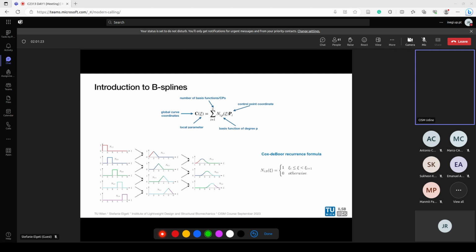Well, here we always have an overlap. So for linear, we have two basis functions that overlap in each knot span. For degree 0, we don't have any overlap at all. And I don't think it's even possible to form a curve like that. No, because if it's degree 1, we replicate the control polygon. If it's degree 0, it is nothing. It's some disjoint structure.